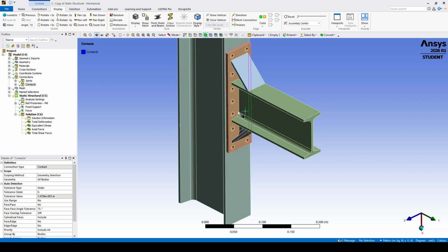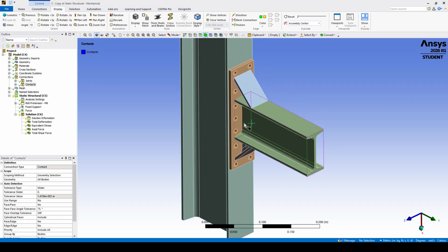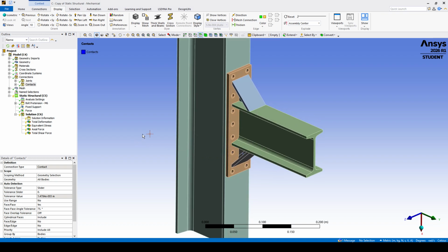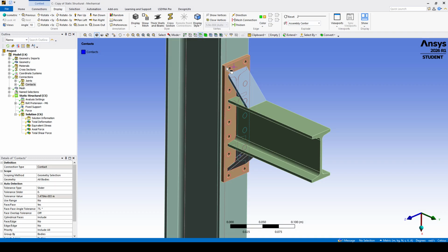So in this case, or in other cases where you have 100 or 1,000 bolts, there's a strategy that you can use to do it in an efficient way, faster and practical actually. So I will show you now how to do this. In order to create these joints fast and efficiently, what you have to prepare first is a name selection of the beams that you have.